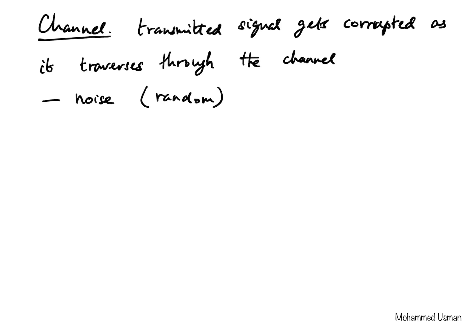So we have to deal with the probabilistic models to characterize that noise, and also once the signal gets corrupted with the noise, then we need to use probabilistic tools to deal with the randomness and to analyze the randomness, and to also devise techniques or mechanisms whereby the effects of this noise can be minimized. Now, the noise typically is considered to be additive. That means the noise gets added to the signal that we transmit. So in that case, we call it additive noise.